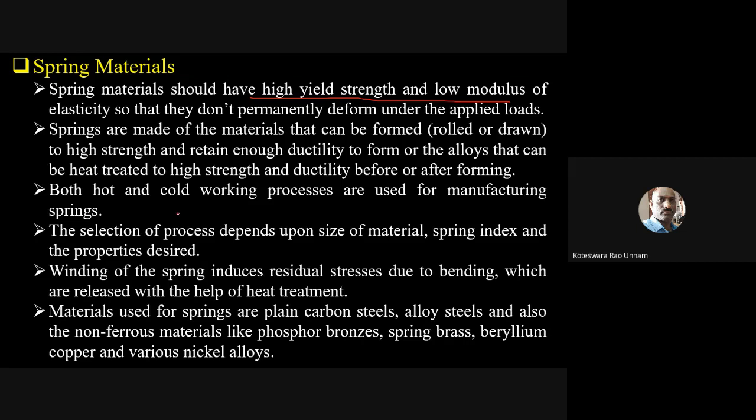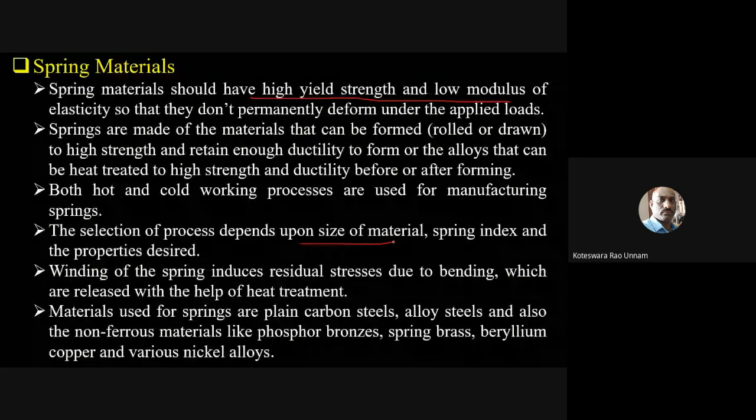Then, the process you select for producing the springs will depend upon the type of material, size of the material, spring index, and the required or desired properties.